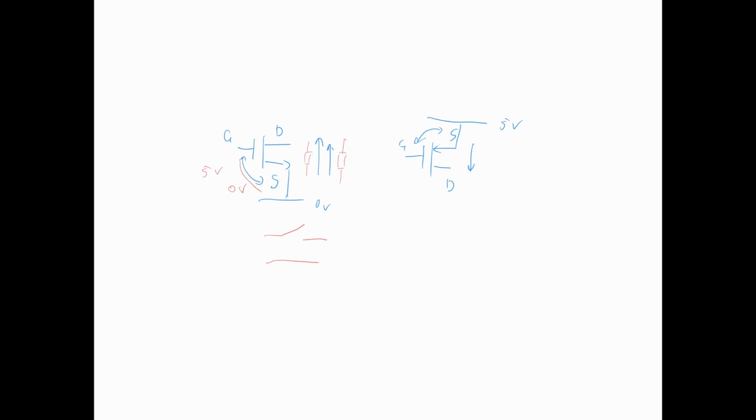0 resistance, ideally. So the more refined model of a FET being a voltage-controlled resistor is replaced by the even cruder model of a FET being a voltage-controlled switch. By controlling the gate to source voltage, we can either have the switch on or the switch off.